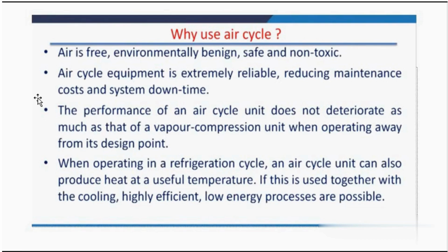Then when we operate the refrigeration cycle, an air cycle unit can also produce heat as a useful byproduct. This heat energy can also be employed to conduct other processes inside an aircraft. If this system is used together with the cooling, then highly efficient low energy processes are also possible.